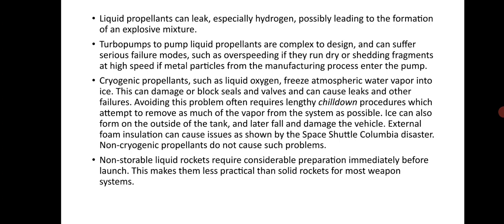Liquid propellant can leak, especially hydrogen, possibly leading to the formation of an explosive mixture. Turbo pumps to pump liquid propellants are complex to design and can suffer serious failure modes such as overspeeding if they run dry, or shedding fragments at high speed if metal particulate from the manufacturing process enters the pump.